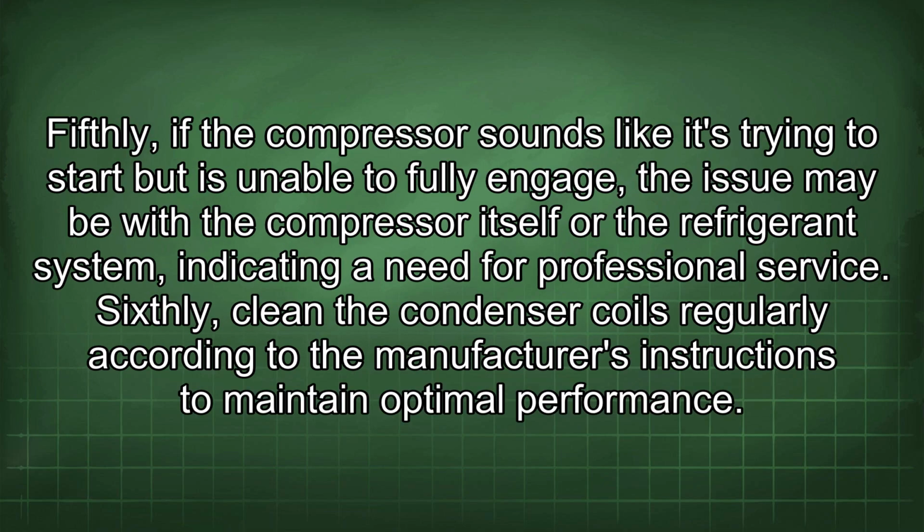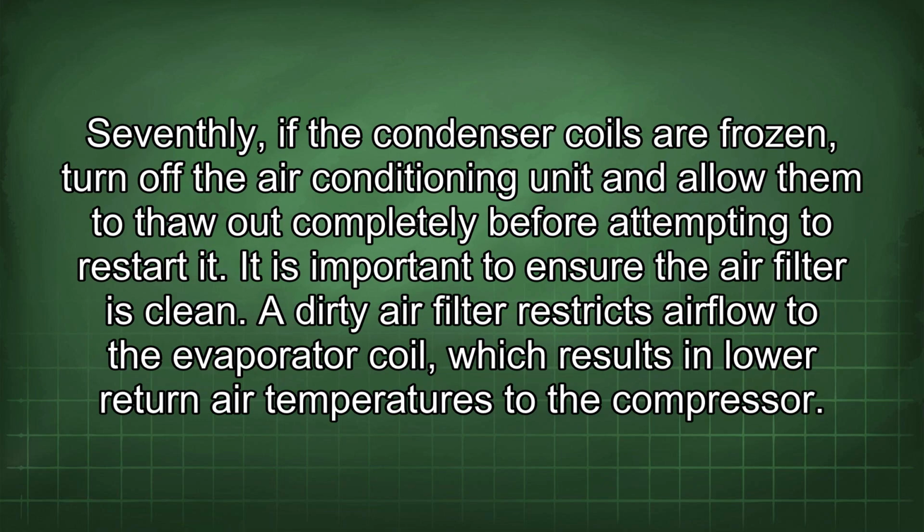Fifthly, if the compressor sounds like it's trying to start but is unable to fully engage, the issue may be with the compressor itself or the refrigerant system, indicating a need for professional service. Sixthly, clean the condenser coils regularly according to the manufacturer's instructions to maintain optimal performance. Seventhly, if the condenser coils are frozen, turn off the air conditioning unit and allow them to thaw out completely before attempting to restart it.